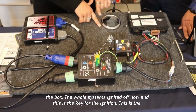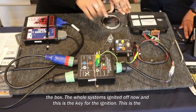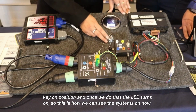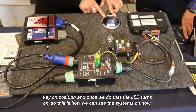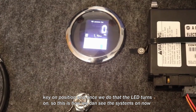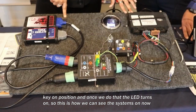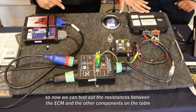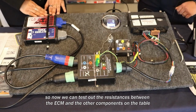The whole system's ignition is off now, and this is the key for the ignition. This is the key on position, and once we do that, the LED turns on. So this is how we can say the system's on now. Now we can test the resistances between the ECM and the other components on the table.